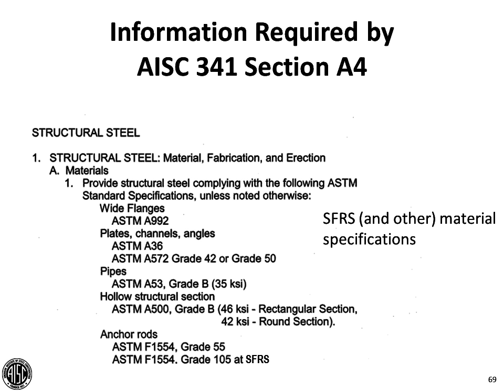Larry mentioned that ASTM A992 steel is not an absolute requirement for seismic systems. It's generally recommended as the primary choice for wide flanges. It has some desirable qualities from a seismic performance perspective in the sense that the maximum yield strength is limited, whereas with some of the other ones it's not. Now we try to address that fact in some of the design requirements using the expected strength factors. But we also have the option of specifying other grades of steel for different functions. And so you can see these here.